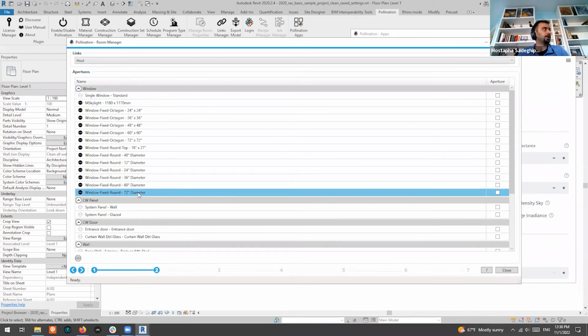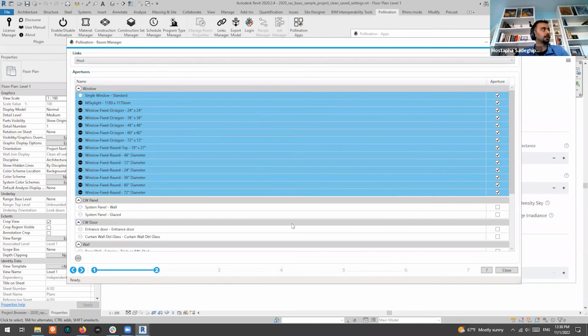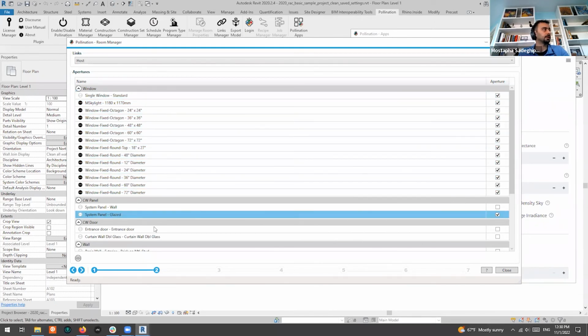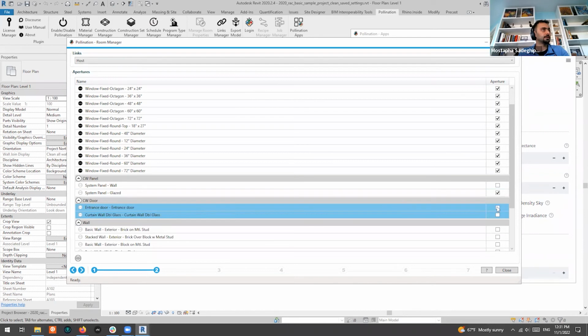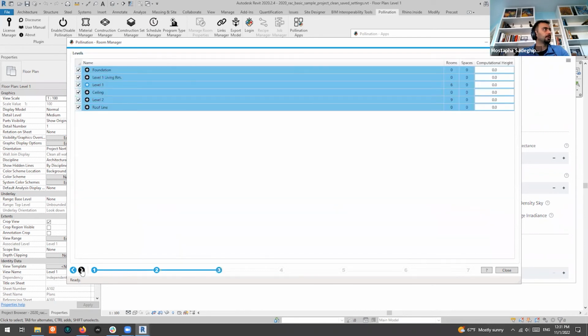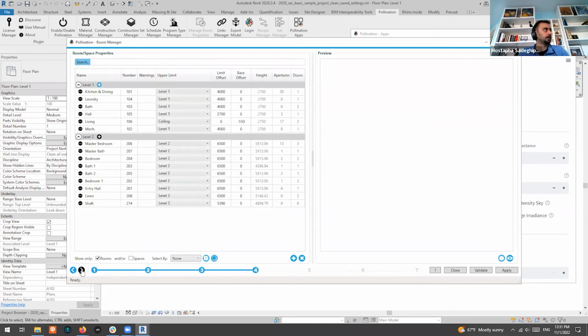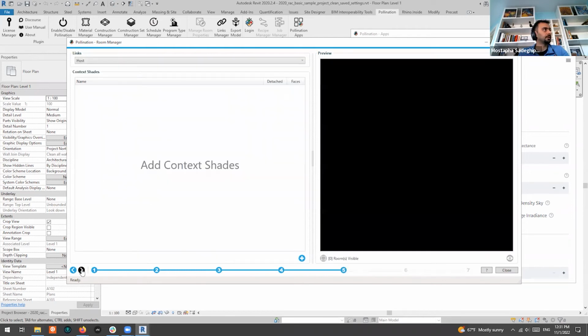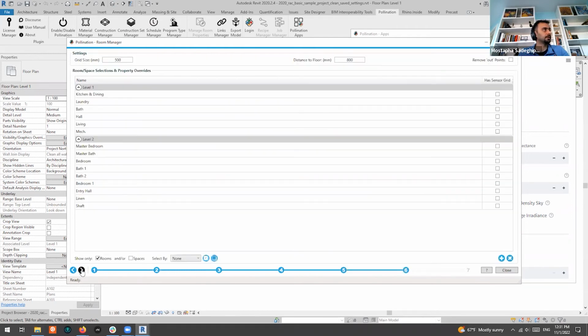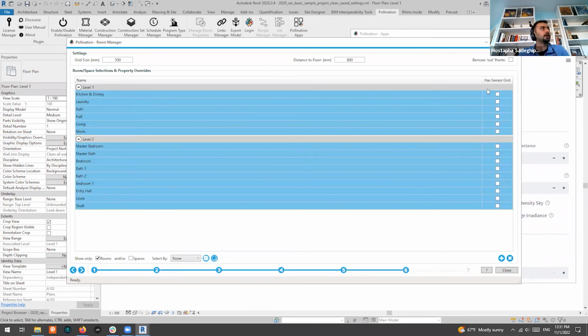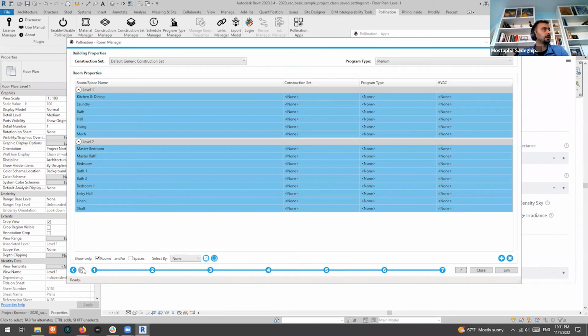Of course, ideally we have to cache this, and you don't have to go through the process every time. Or I should save the changes that I make to my files. But by now you know this process. This model is cleaned up, so it shouldn't be hard to do the steps. The only thing that is going to be different here is I'm going to select them and make sure they have sensor grid. So I add sensor grid to rooms because for the radiation study, you need sensor grid. And now instead of export here, the model will be linked.